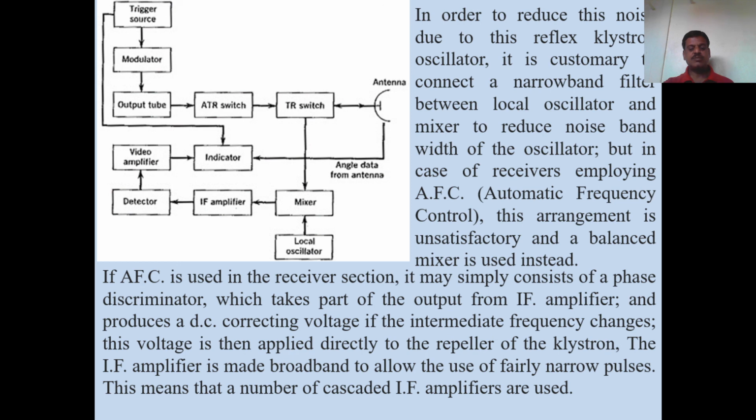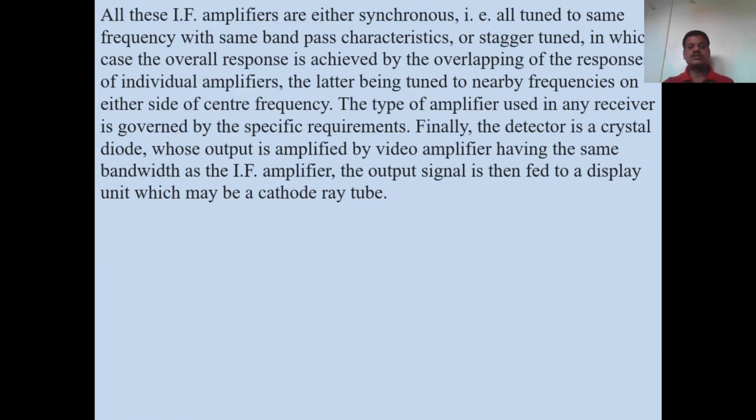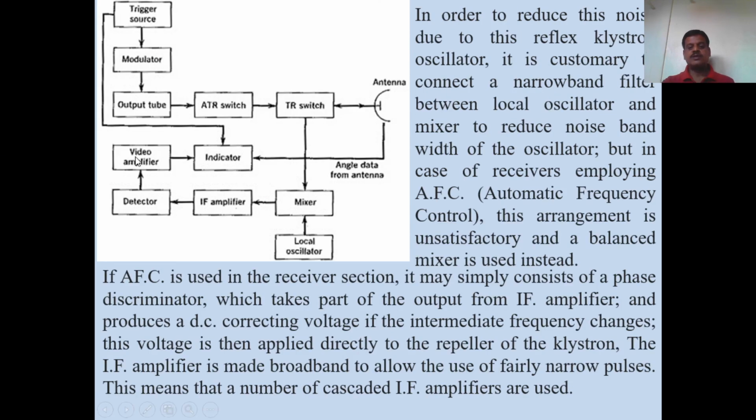This means a number of cascaded IF amplifiers are used in this radar receiver. All these IF amplifiers are either synchronously tuned, meaning all tuned at the same frequency. Overall response is achieved by overlapping the response of the individual amplifiers. Then